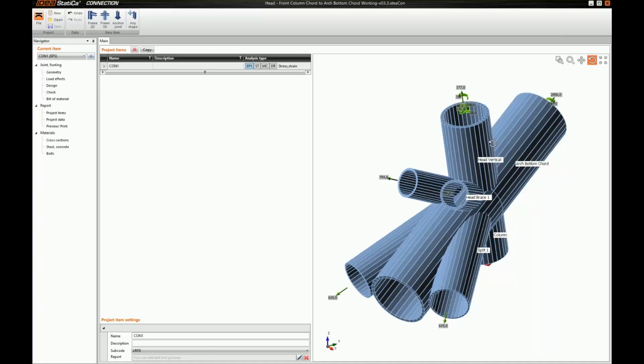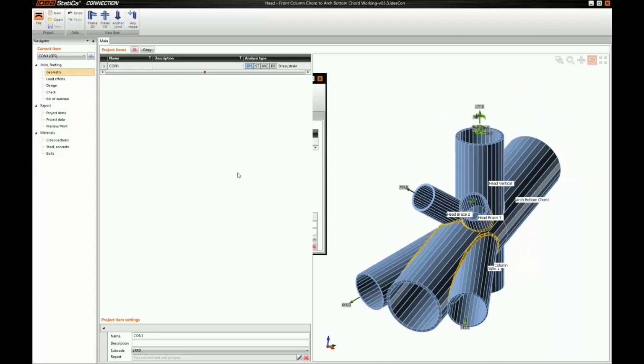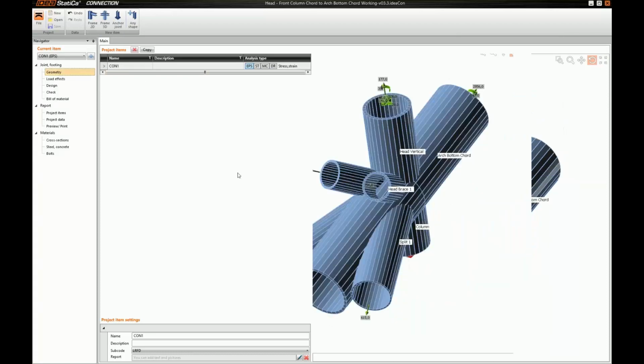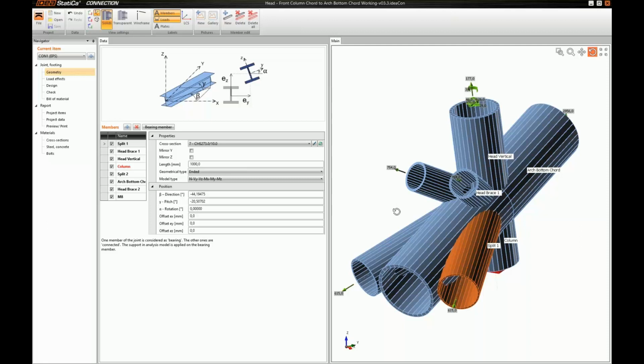The BIM link approach has two advantages. First is that I can have the correct orientation of the members easily, which is essential for this type of connection and saves us a lot of laborious work. As you can see here, for example, the member angles have been inputted from the software with a precision of up to 5 digits, which would be too much work.